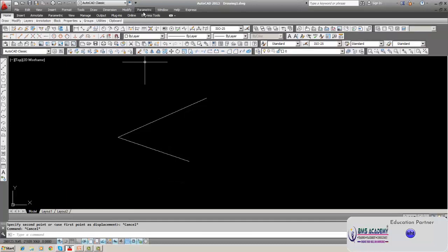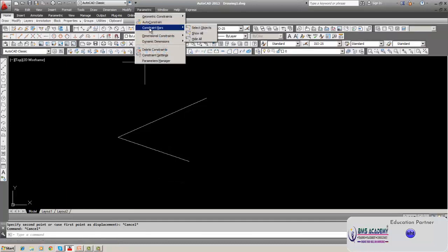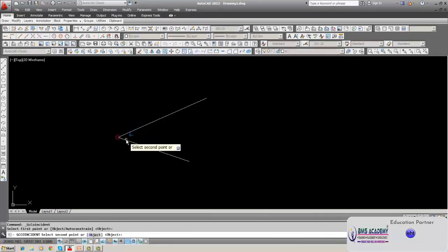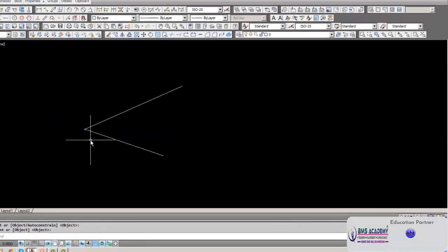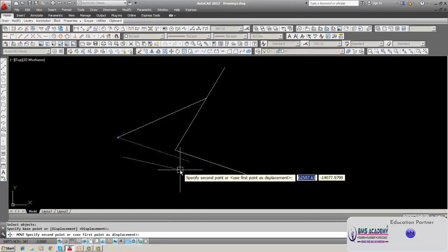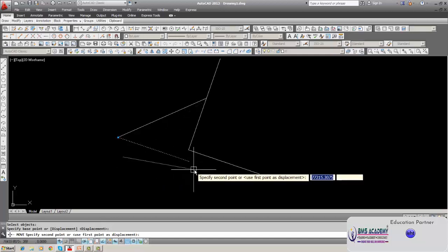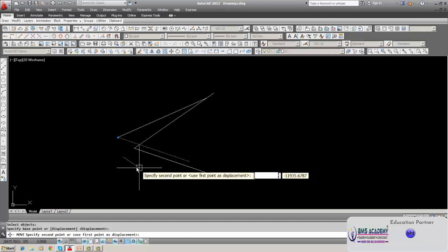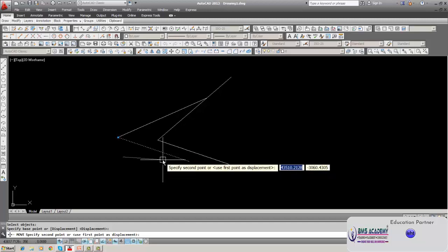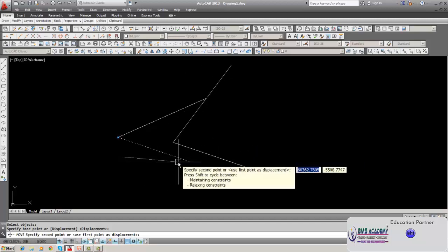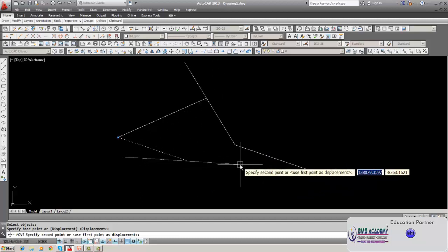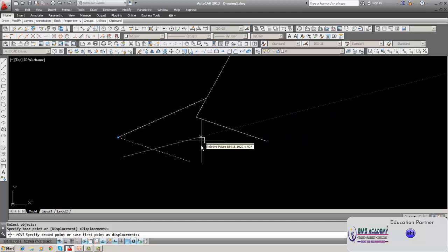Okay. Suppose once again I apply a geometrical constraint. We will talk about geometrical constraint, coincident constraint. So we have to select this. Now, suppose we want to move, we can move like this. The entire thing can move because that side is auto constraint. Auto constraint means the constraint is automatically applied to a point or joint. So we can move it like this. But since at that point this point also is there, it will move like this. This point is automatically fixed.